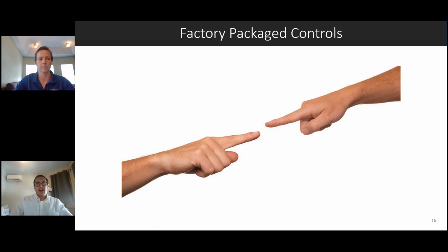But whenever you're actually deep diving individual devices, you do still need to know what we're talking about. Are we talking about an inexpensive little airflow sensor, or are we talking about an Ebtron Gold Series airflow measuring station? Those are two completely different cost categories, and you need to usually look to the specs to determine that.